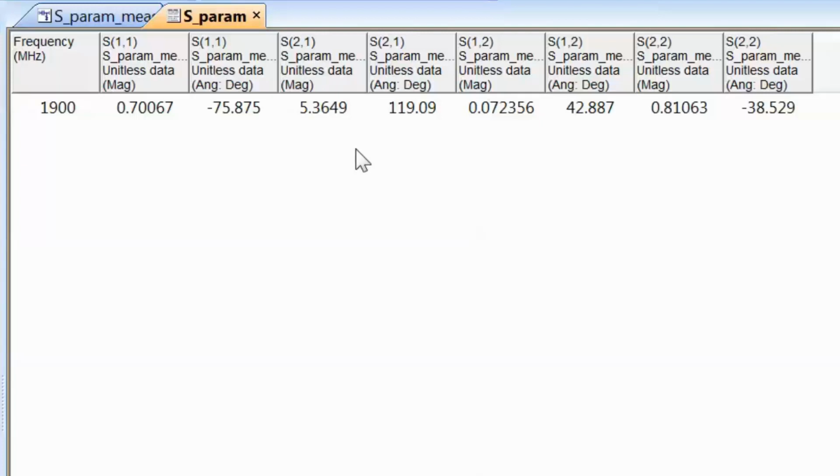The S11 and S22 parameters may become greater than unity since you have an active circuit, but when that happens you end up having feedback effects, and this can cause oscillations, so that's really bad news. Also, when you have a transistor which is not matched, and you've just measured the S parameters with 50 ohm terminations, which may mean that the transistor is not operating in a region where it can provide gain, the S21 may also be less than 1. So these are just a few pointers to bear in mind.